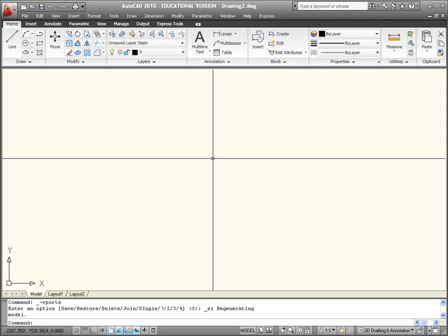other. In paper space, we'll see that you can have what's called floating viewports, and they can be any shape or size. You can move, copy, scale, stretch them. You can have as many of them as you need, and this is controlled by a system variable called tile mode.